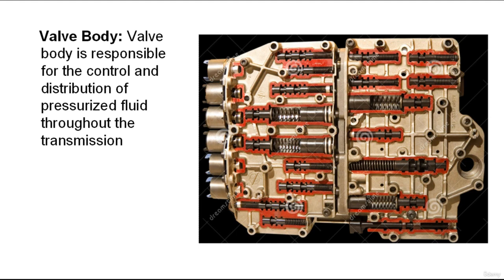The valve body is machined from aluminum or iron and has many precisely machined bores and fluid passages. Various valves are fitted into the bores, and the passages direct fluid to various valves and other parts of the transmission. The separator and the transfer plate are designed to seal off some of these passages and to allow fluid to flow through specific passages. The purpose of a valve body is to sense and respond to engine and vehicle load, as well as to meet the needs of the driver.